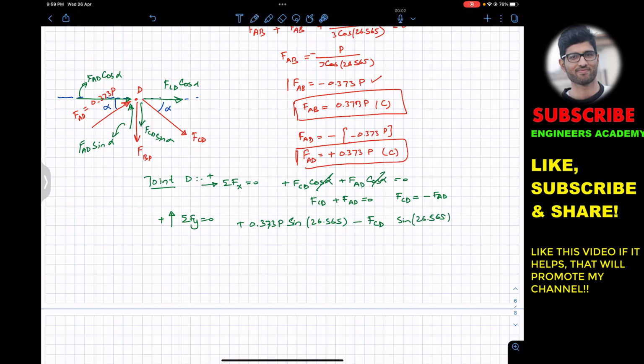And now we know that FCD is equal to minus FAD. So from this we can say that FCD is equal to minus FAD, and FAD is 0.373 P. So the minus sign tells us that the assumed direction of FCD is not accurate. FCD is acting towards this joint D, so this means that FCD is also compressive force. So we can say that FCD magnitude is 0.373 P, and it is the compressive force.